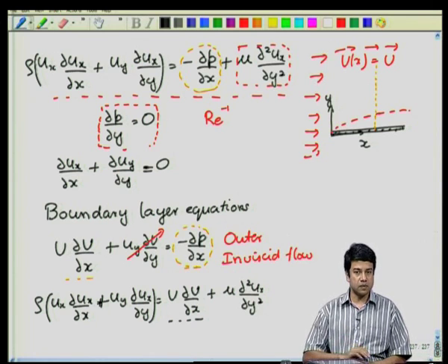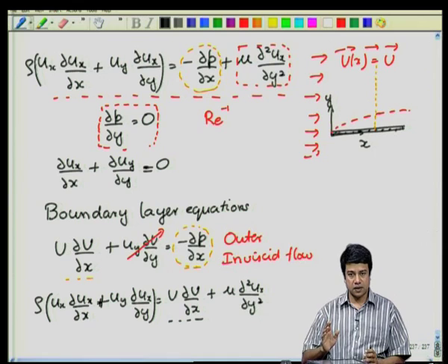There is one more little bit of information that we need before we solve this equation, and that is that the velocity at a given location x does not depend upon the total length L, but on the distance x itself, because the total length is downstream of the plate. We will use that in the next lecture in order to get a similarity solution for this flow past a flat plate.